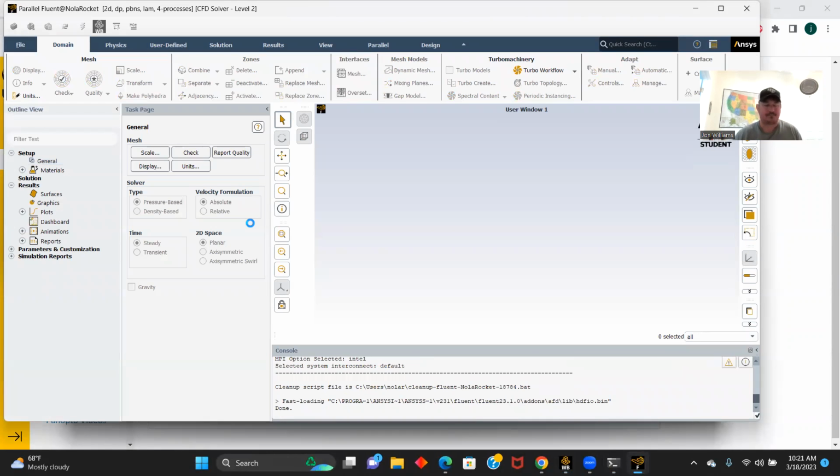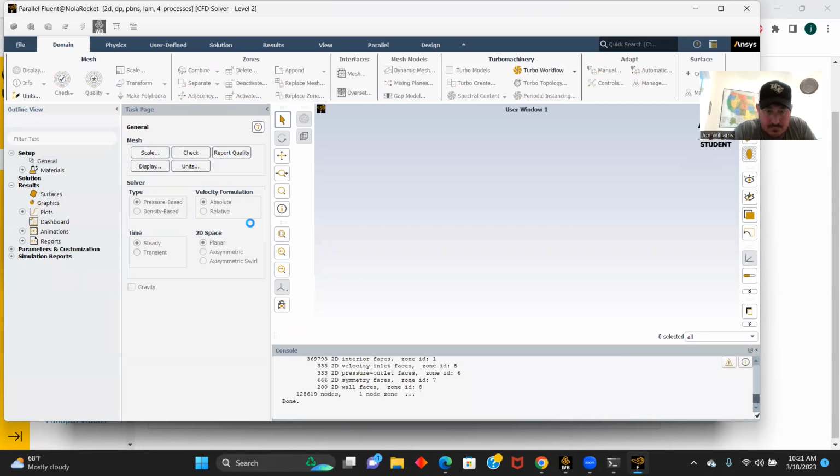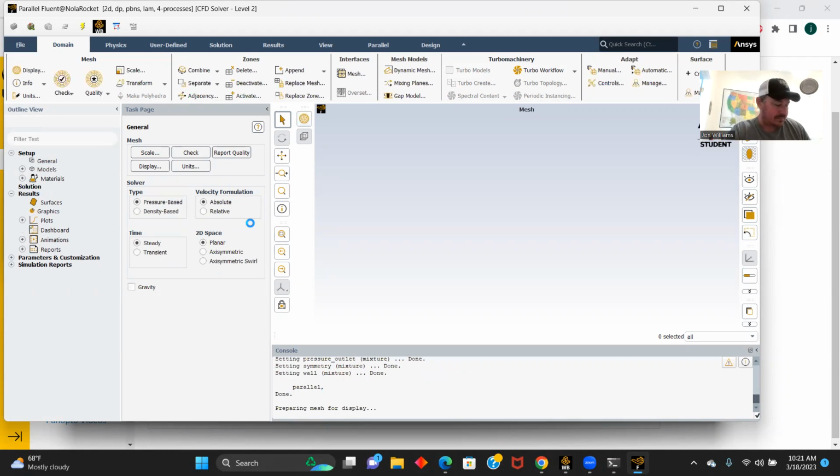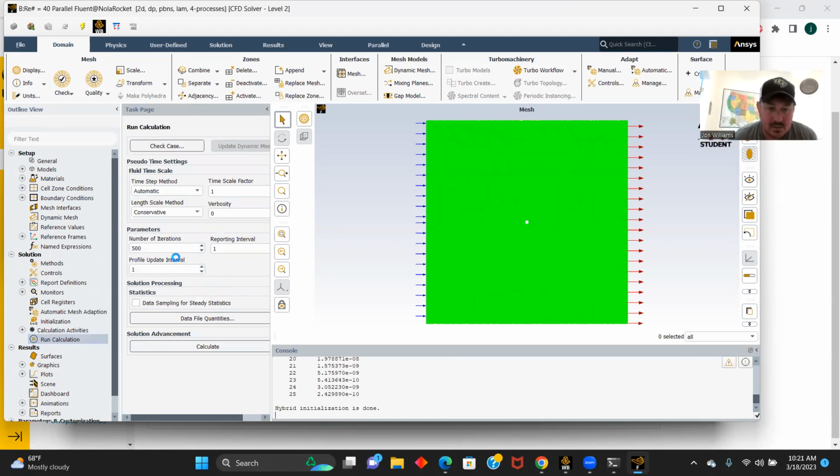And it's thinking again. For this particular case, we're going to be using a viscosity of 0.5 kilograms per meter second. And we're going to have a fluid flow of 20 meters per second for velocity. Done. Okay, so let's come back up here.